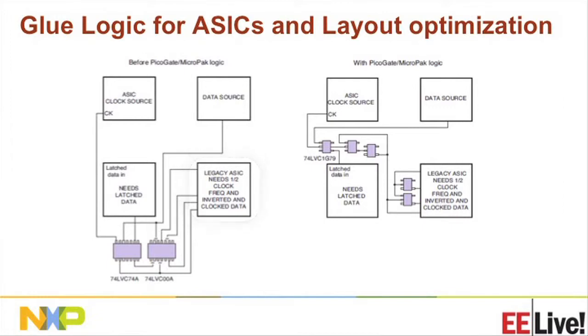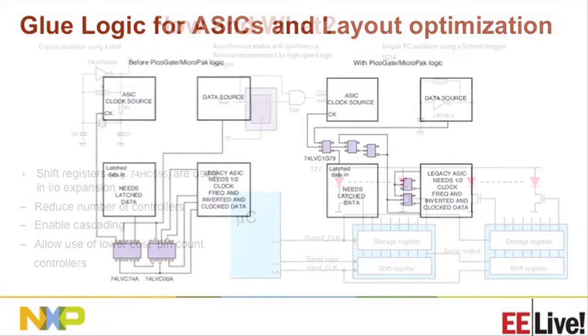So in the past, this was done with the standard solutions, which were higher pin count. Even if you had to use a couple of channels there, you would end up getting the whole package, and that would take a lot of space, and the layout would look messy. So today, we offer solutions which are up to 6 lead. Again, those are single, dual, and triple gates. You can do a clean routing, save some PCB space there, and it optimizes the whole board.